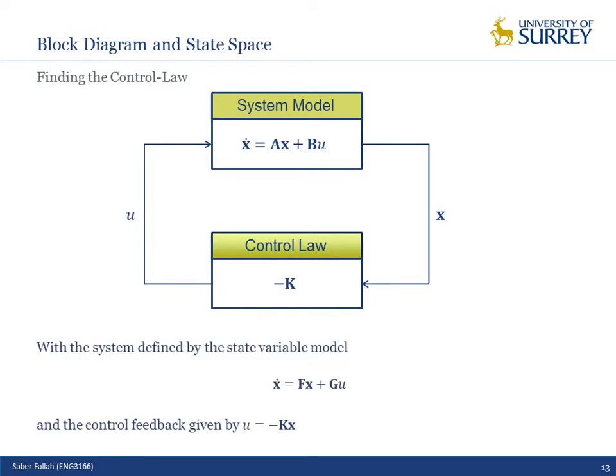So if I have the system modeled by x dot equal to fx plus gu, again, we use this relation just for simulation. In reality, we don't have such a relation. We have a physical hardware. But in order to simulate our control or system, we need to have some representation of the dynamic response of my system. The response is modeled by this state space format. The objective is minus kx. This one is the software part of your real control system.